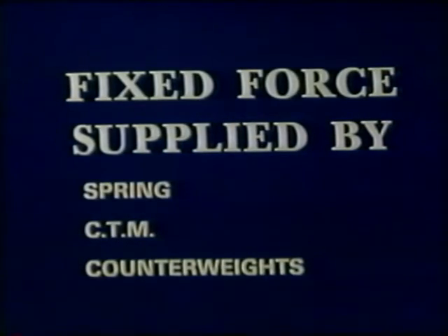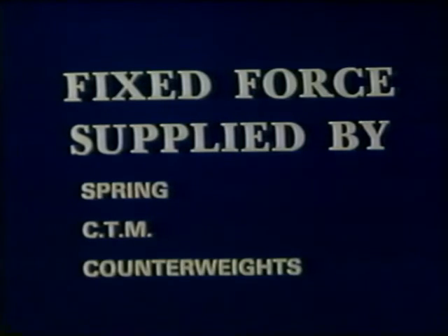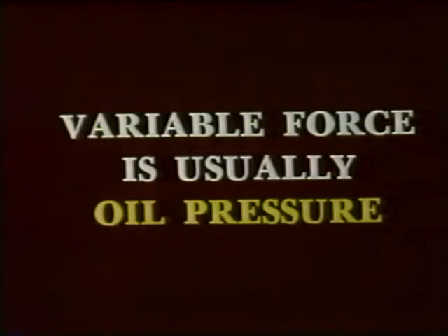Constant speed propellers use a fixed force to cause an increase or decrease in blade angle. This force may be a spring, centrifugal twisting moment, or centrifugal force acting on a counterweight. The force is termed fixed because it is always present during operation and must be overcome to change blade angle. The most commonly used variable force, which will cause change in blade angle opposite to the fixed force, is engine oil pressure. The oil pressure is varied by the governor as necessary to adjust the blades to the desired angle.